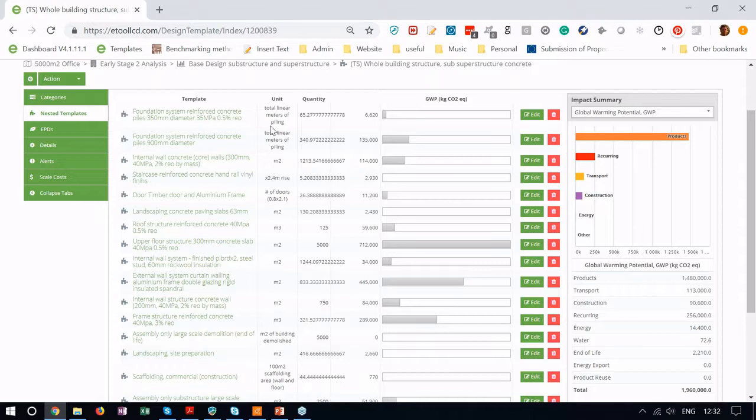You know, what's the difference between a concrete slab and a composite metal deck, a steel frame or concrete columns. Anything that we can do with the foundations to improve the efficiency there, or maybe alternatives in terms of the material choice, looking at fly ash, ground granulated blast furnace slag. We can see already where I want to focus my attention. It's this upper floor slab. Are there any efficiencies that can be gained there, or alternative materials? External wall, curtain walling system. How does that compare to another system?